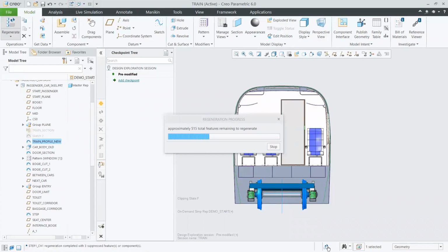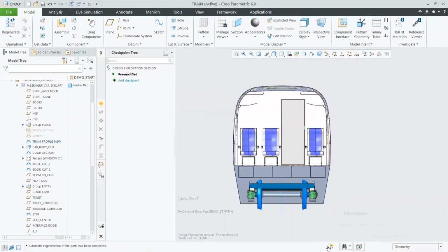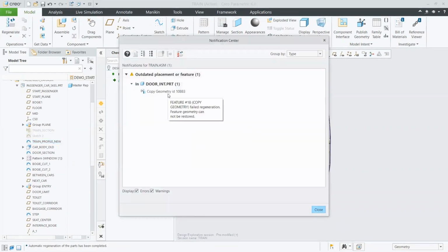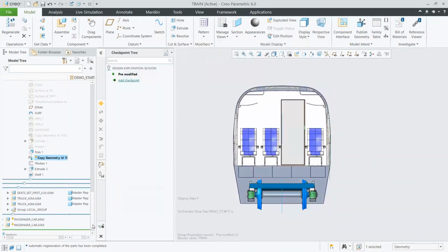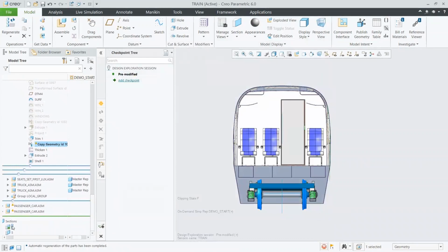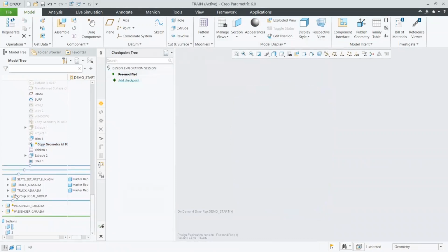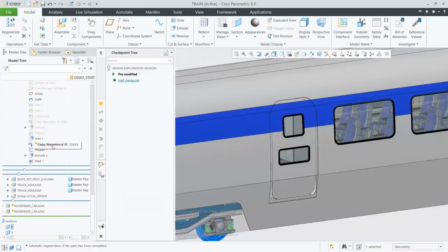And what is that going to do then to everything that we've designed based off of this, right? It obviously has a lot of different effects. Well, in this case here, you can just see that everything changes because it was defined from that skeleton. And actually, it looks like one thing wasn't automatically updated, and that's actually because earlier we had set it to be manually updated with a notification, right?